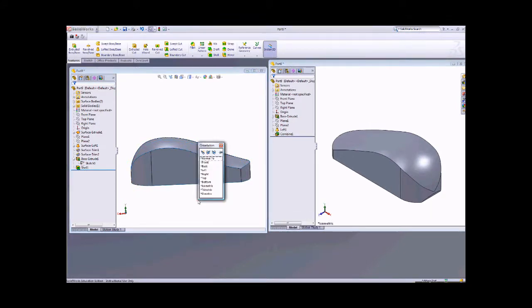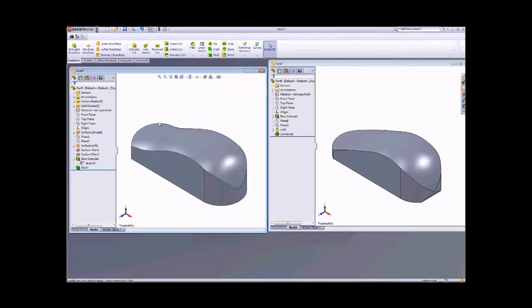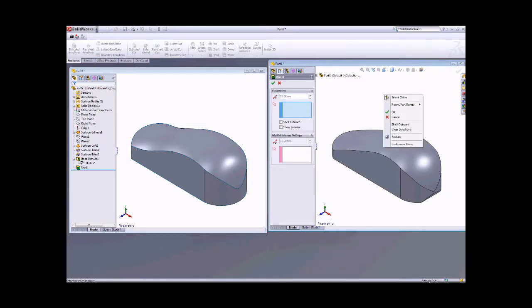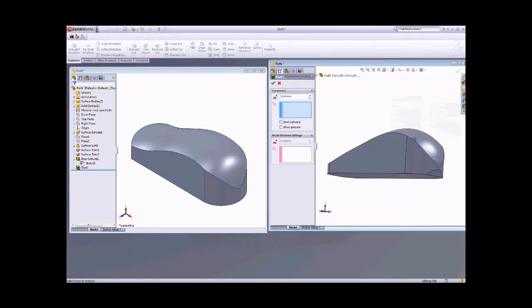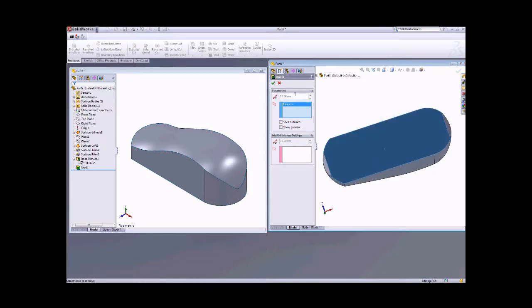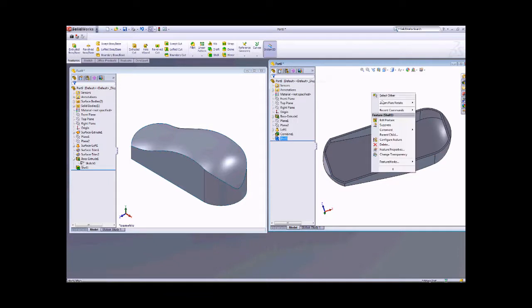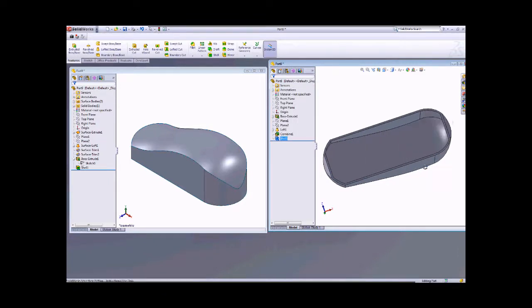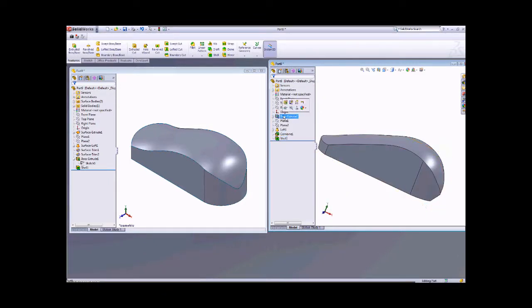So when you go to the isometric view, you can see that one, and then when you want to shell it, you can shell and then turn to rotate to back view, 2 millimeters, and then shell it. So you can see that one is the solid model, because we use the solid model for the extrude.